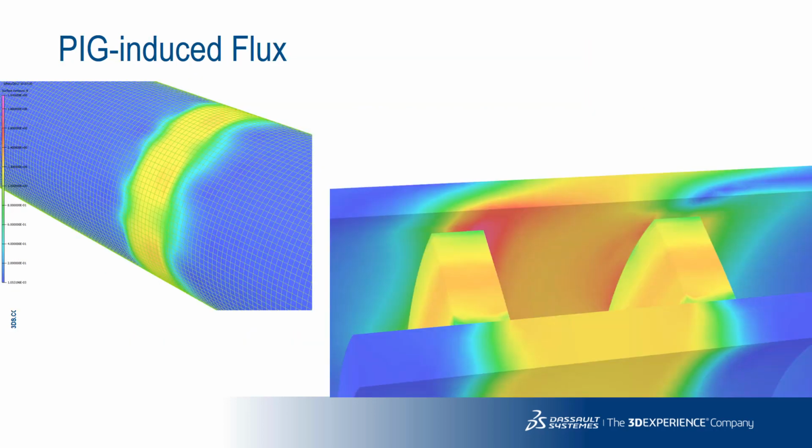For this design exercise, we use a dynamic solution whereby the relative motion is considered not to change the finite element geometry. The source fields and driving conductors are considered to be time invariant. We'll solve for only one position, so consider the PIG effectively to be moving along the inside of an infinitely long pipe.